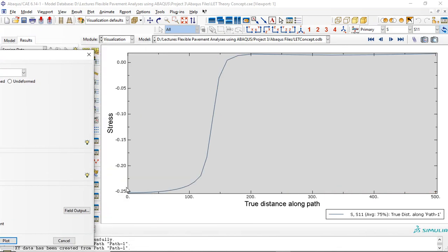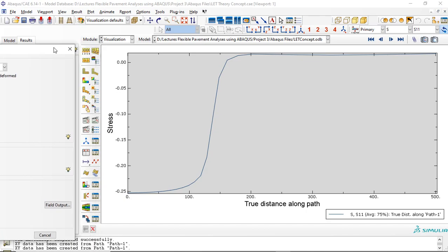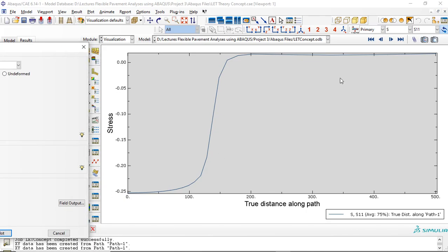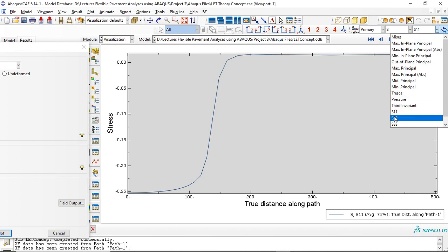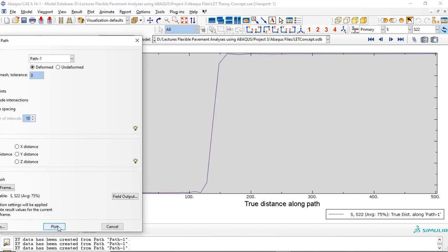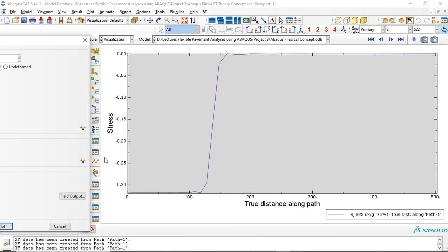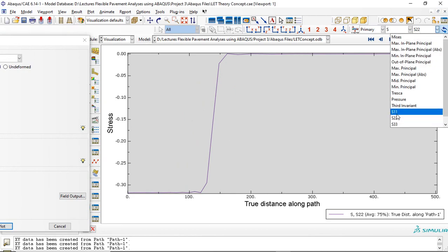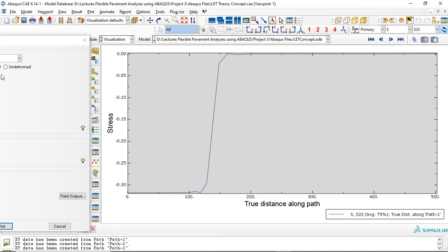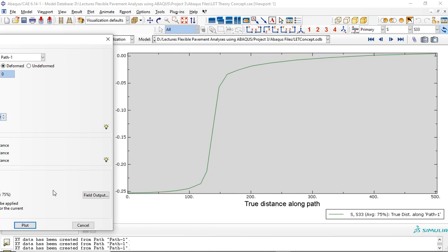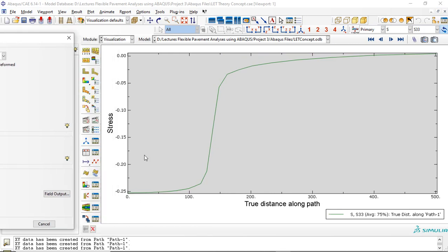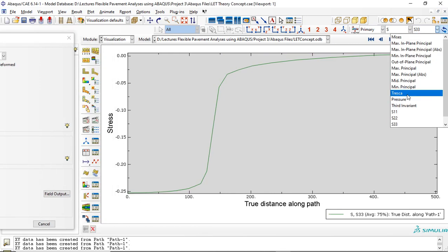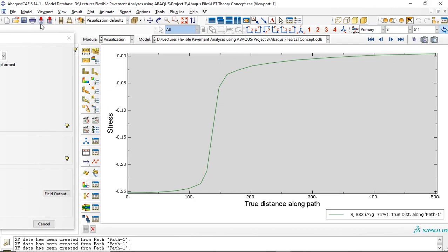And the stresses will be higher since we are using the S11, that's the shell component for the first direction, and for the second direction these will be kind of no different, a little bit amount of difference will be present in these model, and S33 will be 0 here because we are using shell element, so it's approximately at these region it is 0 here. So S11 that we are using here,